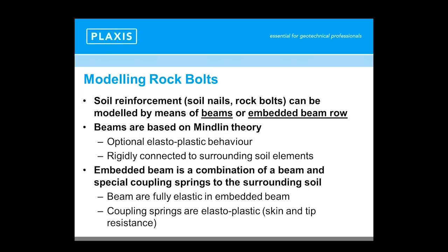When this value of the skin resistance is reached, then the beam element will start sliding inside the soil and no longer be able to transmit any further shear stresses, leading most likely in your model to stress redistribution with surrounding elements which still have some remaining capacity.